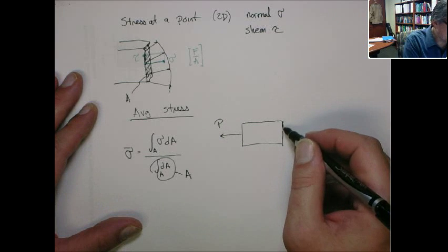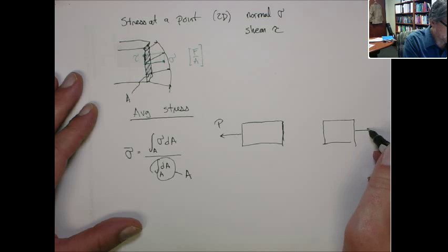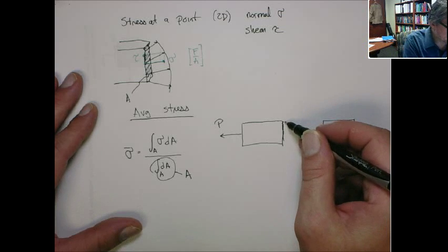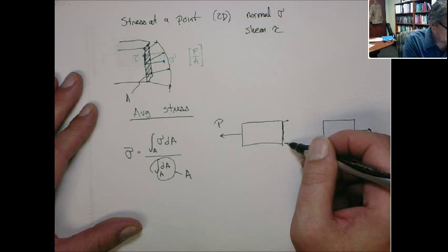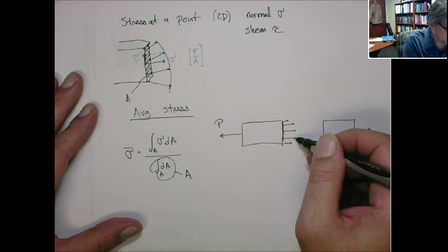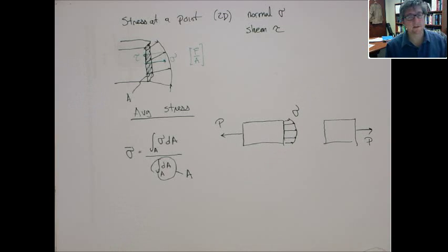This is the cut surface. There's actually another part to the right that we're going to keep down. On this surface, we see the internal tractions. Let's just look at the normal ones. We'll probably have some parabolic distribution. That's the actual stress.